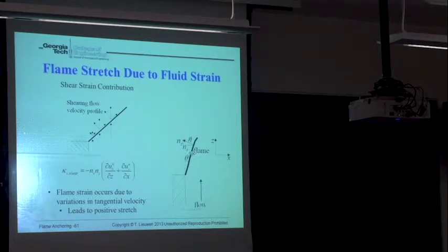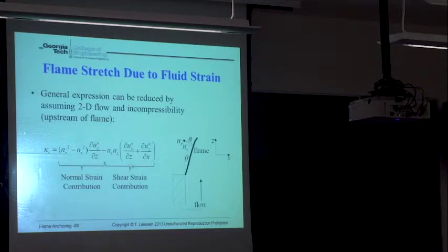But anyway, what you can see is it leads to positive stretch, shear does. But from what I've just shown you, you can see that the stretch rate is a really sensitive function of the flame angle. Again, if you don't know if the flame angle is 1 degree or 5 degrees, which might sound close enough for lunch, that's a factor of 5 difference in flame stretch rate. Okay, so anyway, that's this term right here. So that is how shear is leading to stretching of the flame.